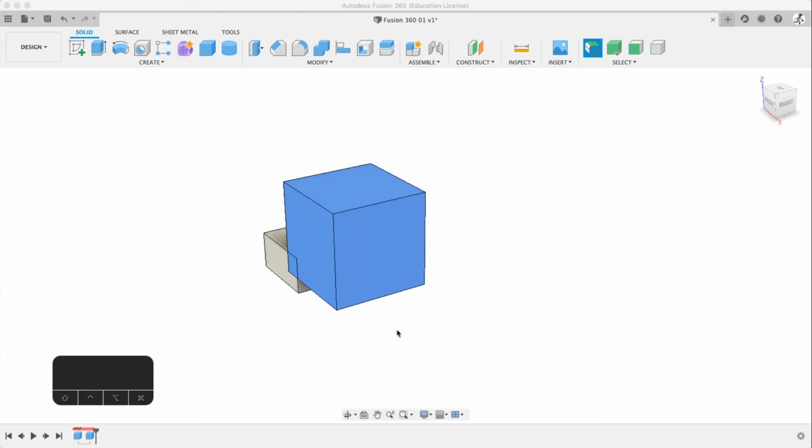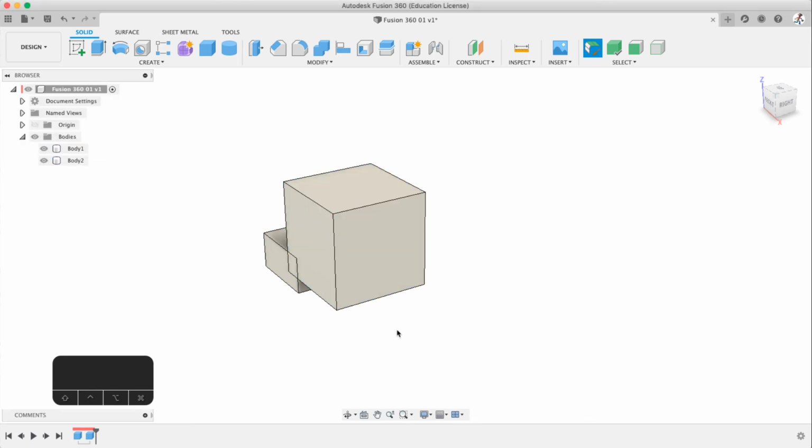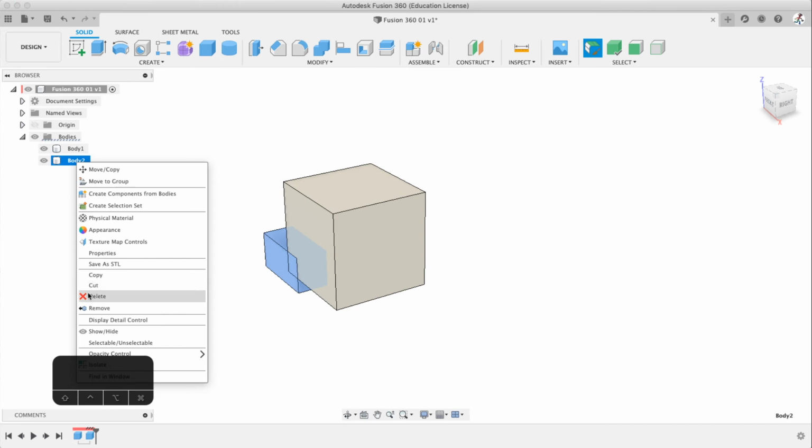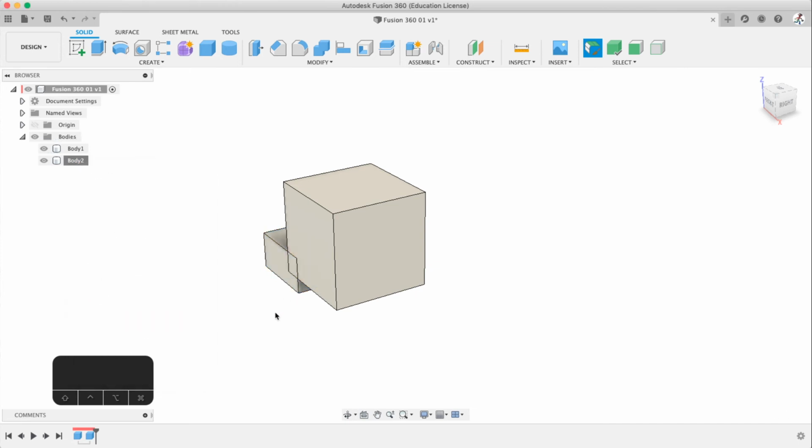then you should really never use delete. There's a few reasons you would use it, but trust me, do not use the delete option. Never delete. Just use remove. And I'll talk about that in a future video. You can turn the history off down here. Do not capture design history.